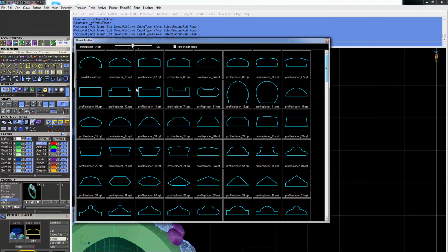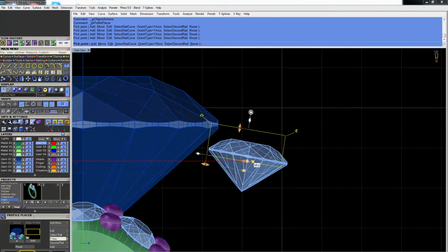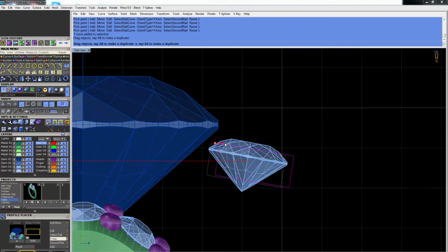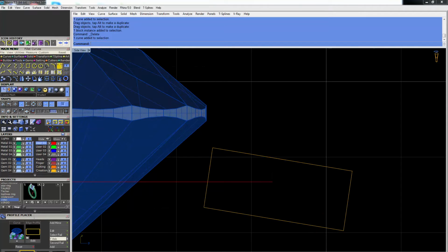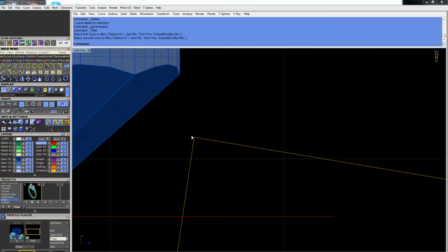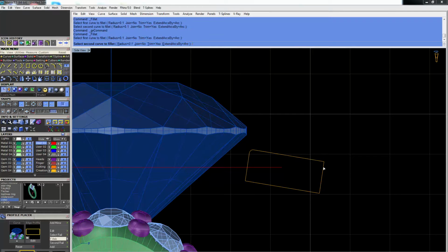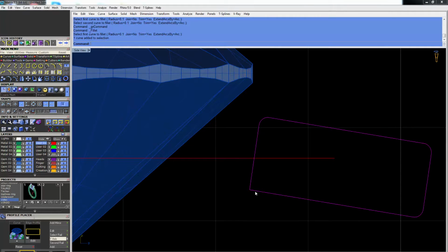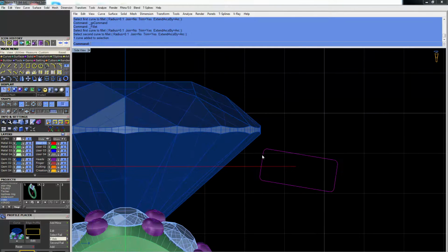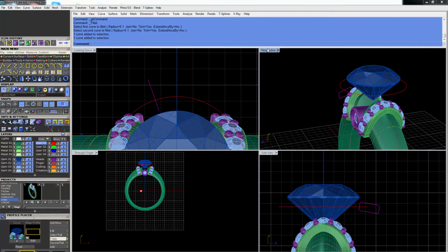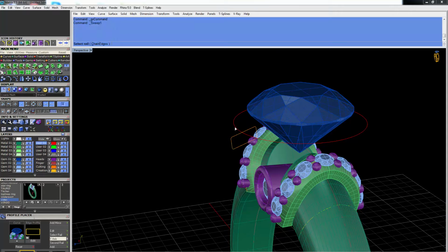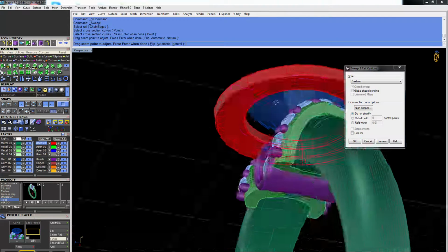Move it down. Oh, it's also important, try to avoid sharp edges, basically because on the render it's not going to look nice. So I'm making just an offset, not an offset, hang on, fillet on the edges. Okay, and now, oh, hang on, this is not okay. Well, yeah, it is okay. I can make surface, flip, one rail, so that's a rail and that's a profile. Enter, enter. That's my halo.